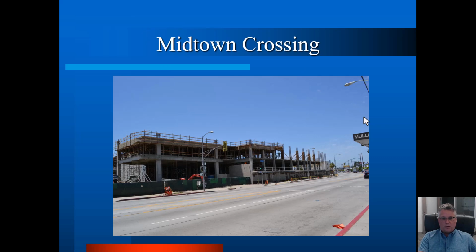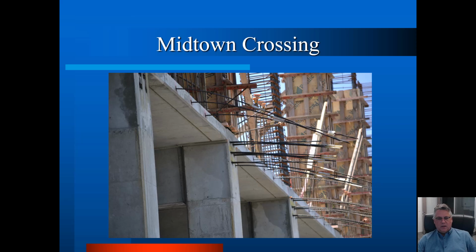This happens to be a project that was close to UCLA, and in 2012 I brought a handful of students over to see what we were talking about. So I took some pictures. This is a picture of the tendons coming out. They have been stressed. The stressing of those tendons allowed all the formwork to be removed. So the steel beam forms were removed, the slab forms were removed. This happened 4 days after pouring the concrete.